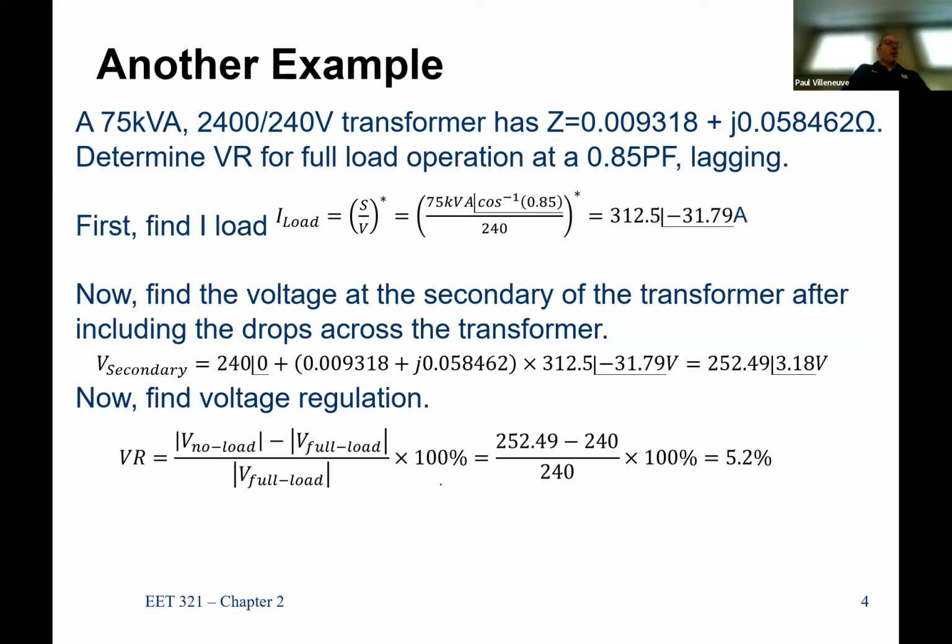You'll also notice outside my office, there's a little concrete step. You have to walk up and into the room where the transformers are, because if any oil spills, you want it in some sort of containment. So they basically have a containment berm built into the flooring. If you look, it's, I don't know, 4 or 6 inches right below the door, so all the oil would be contained inside. So anyway, that would be the transformers that they have inside the basement of Barrows, 2400 to 240.